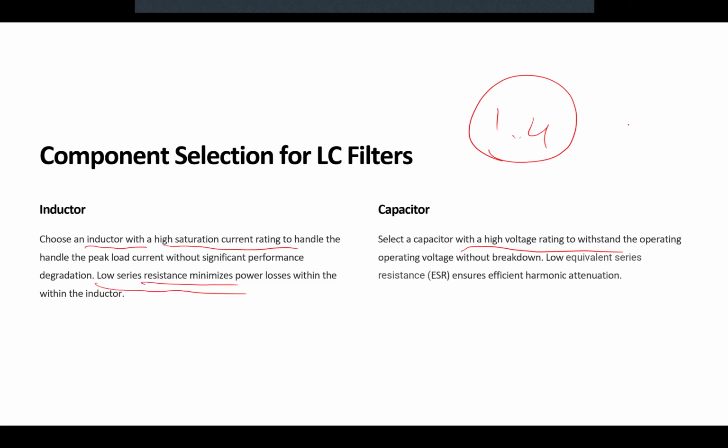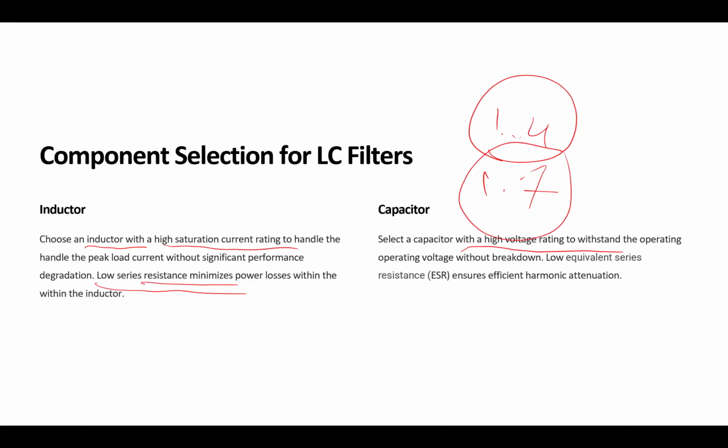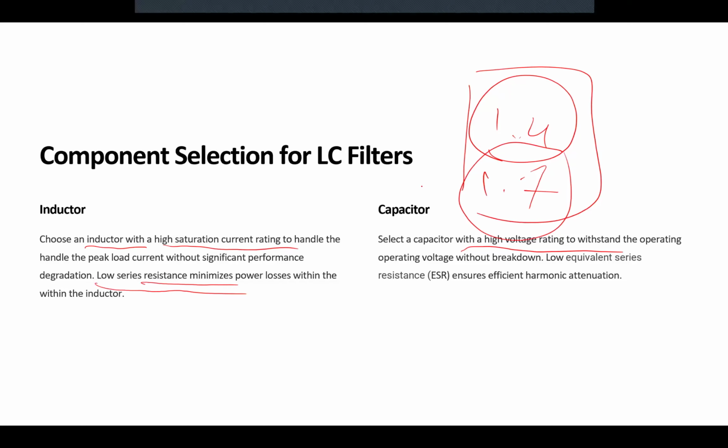It has to tolerate that amount in steady state, and 1.7 for transient, for a short time, of the nominal voltage. Okay, that's why I'm saying that the standard is important, because you see, I'm getting these numbers from the standards for capacitors.